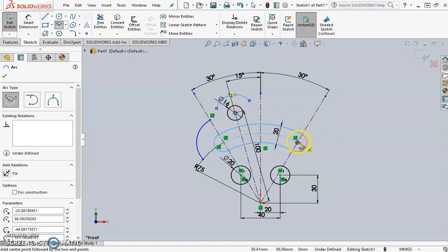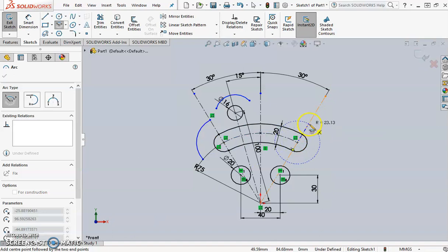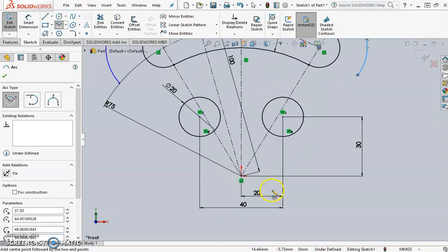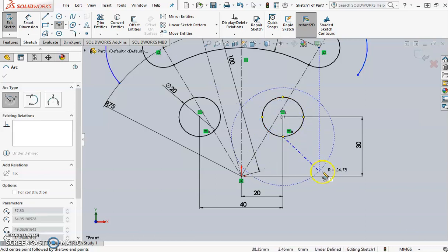Okay. I'm going to do the one on this side. Follow your construction line. Just wrap it around somewhere. And now the two that are a little bit strange. If you move your mouse over your circle and just pause, you'll notice that there's 4 little yellow diamonds that pop up. The bottom diamond is going to be our center point. So we want one that's just here to here.